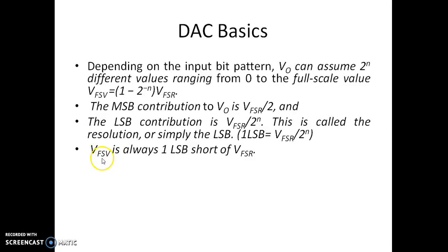VFSV, where VFSV stands for the full scale voltage, is always 1 LSB less than VFSR. We know that this is VFSR, so the full scale voltage is VFSR minus 1 LSB. So VFSV is actually 1 LSB shorter than VFSR. That's what is given here.